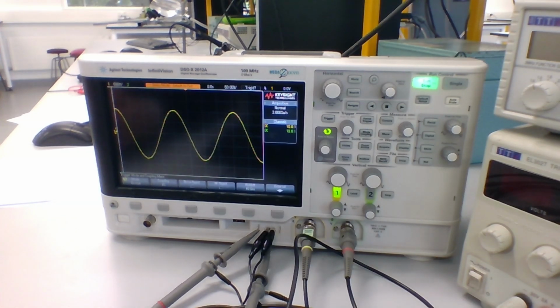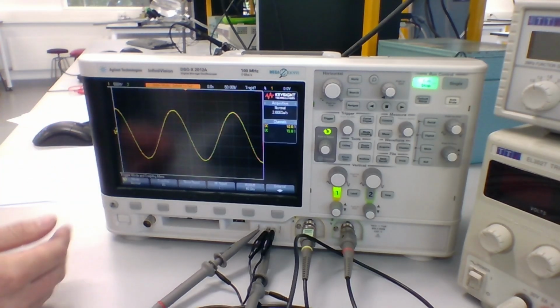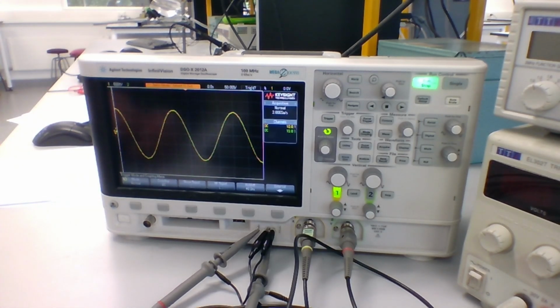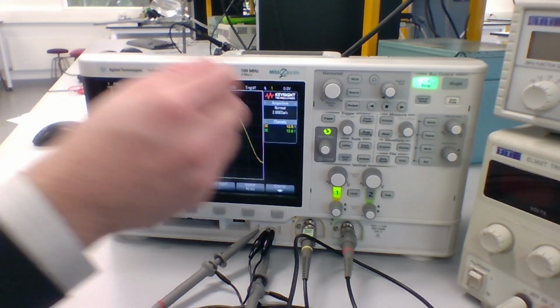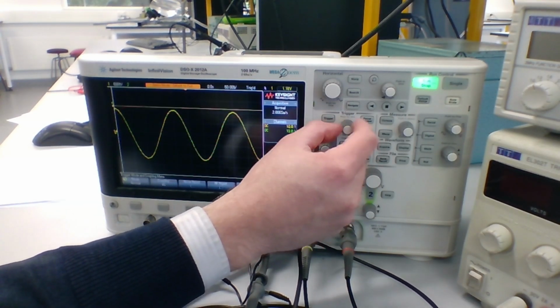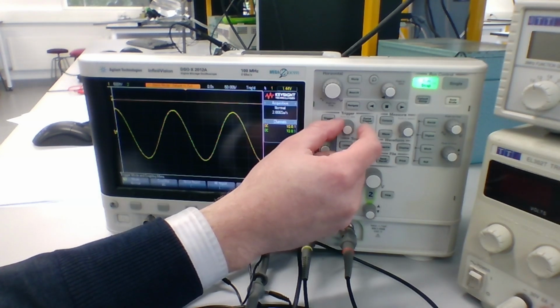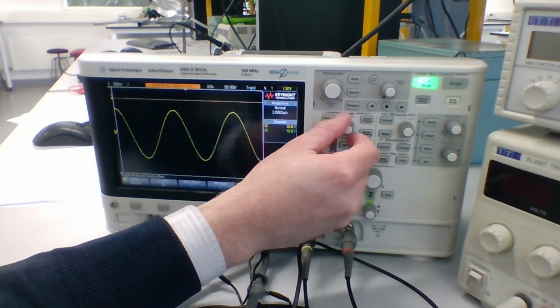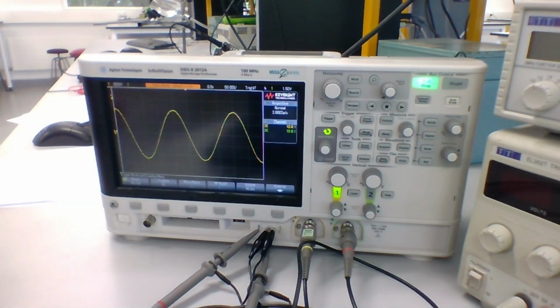So when the probe disconnects, nothing is hitting the trigger. There is no falling edge going down below 0 volts. So the oscilloscope in normal mode says, okay, well, I'm going to retain the last thing I had on screen. Okay, we can then change this trigger level up to 1.5 volts. As we do that, we see nothing changes again. There's been no update of the trigger, so in normal mode, nothing changes.